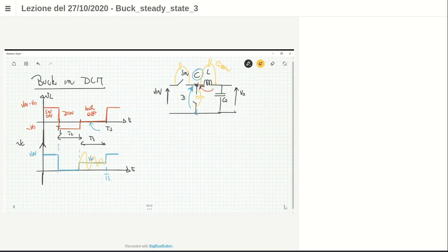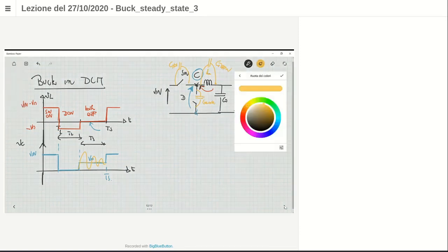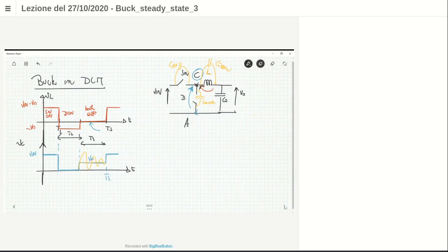So when all the switches are open, you have to consider that in that specific situation you have a resonator. The resonator is composed of C MOS, C diode, and C term in parallel, and the inductor which is formed by the proper inductor of the buck. So in terms of the AC circuit that holds for this kind of ringing, the V in voltage, which is constant, can be considered a short circuit. The output voltage is a constant, which is also considered a short circuit. So just for AC, you can have this kind of circuit here.